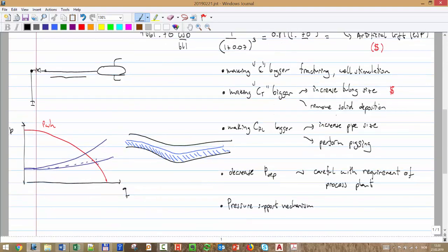Remember, here, when we are operating at plateau, we have a pressure drop in this choke. So basically, that pressure drop, you have to see it as a waste of energy, burning energy in that localized component. So if I can use that energy for anything else, for example, I have a gas reservoir, I can use high pressure gas to make gas lift in some other field.